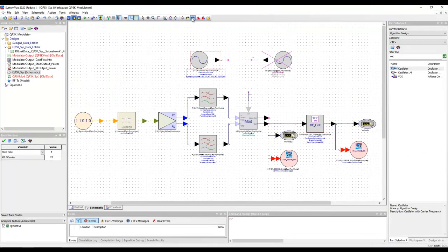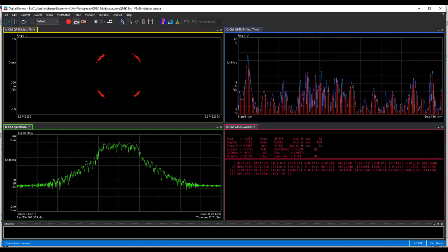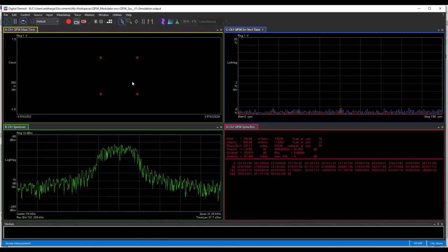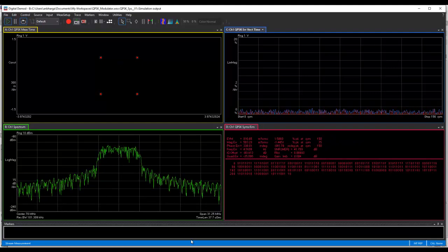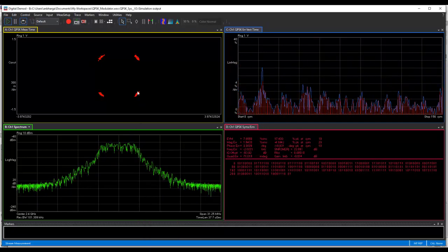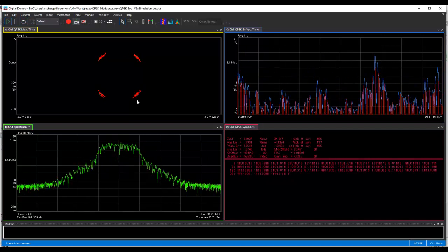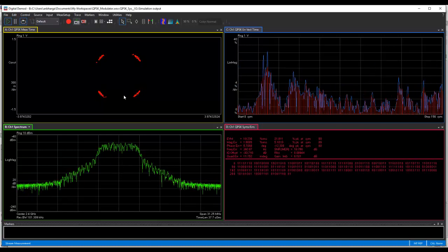So let's go back to our original condition where we had a clean source going from the data flow domain, but we have enabled the phase noise from the LO inside the transmitter. And let's look at the performance here. So first, let's go back to our IF here. And in IF, you can definitely see it's a clean system, no phase noise coming from the digital system. However, if we look at the response here, we can see the phase noise caused by the RF transmitter local oscillator is giving a bad EVM, and we can see the corresponding impact.